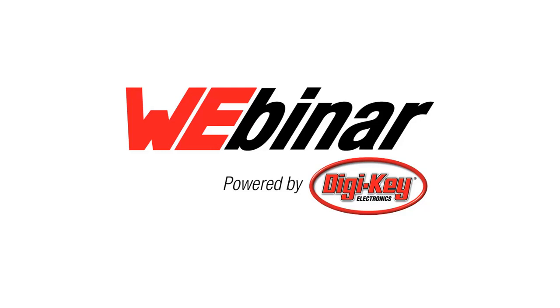This next one I also believe goes to you. This person has read that a USB PD source needs to advertise whether it also works as a data DFP or is dataless. What does the sink do with this information? And what if they use a PD controller that advertises no data, but still try to send data through an autonomous MCU? Are they still able to send that data?